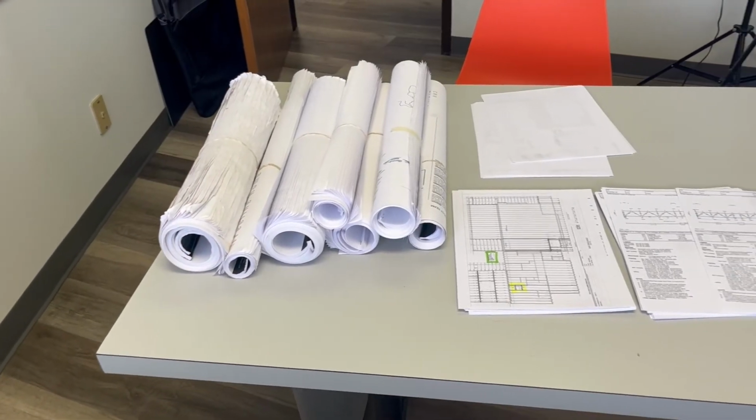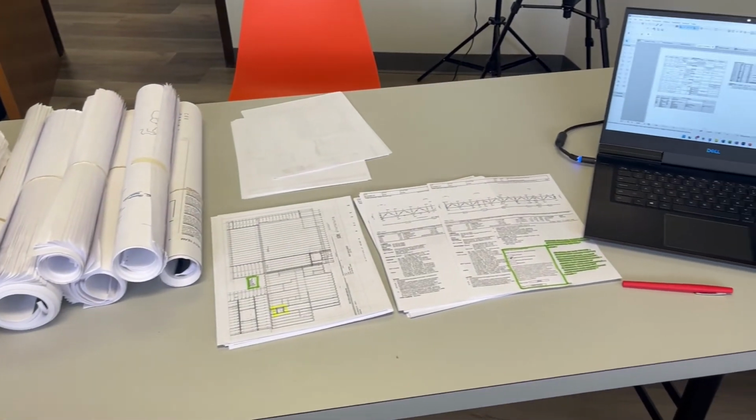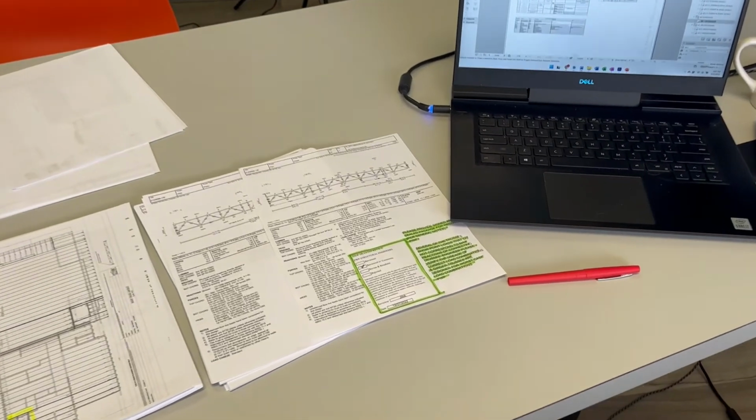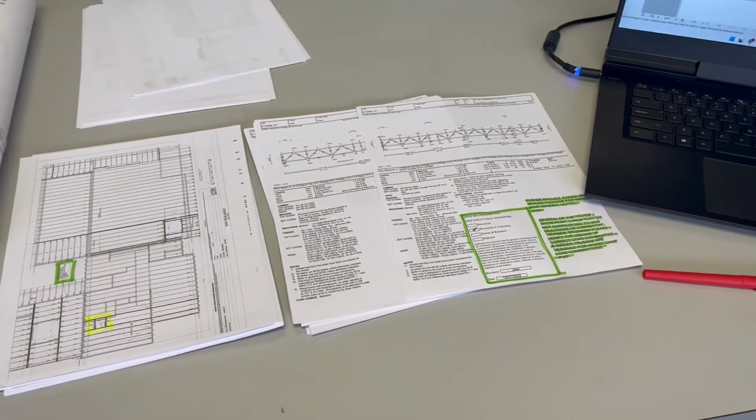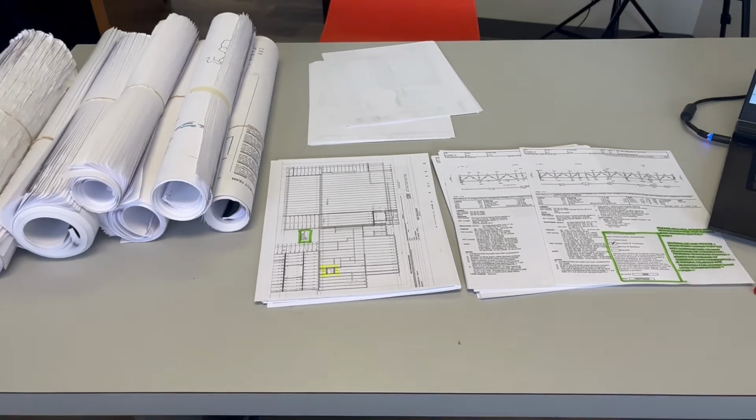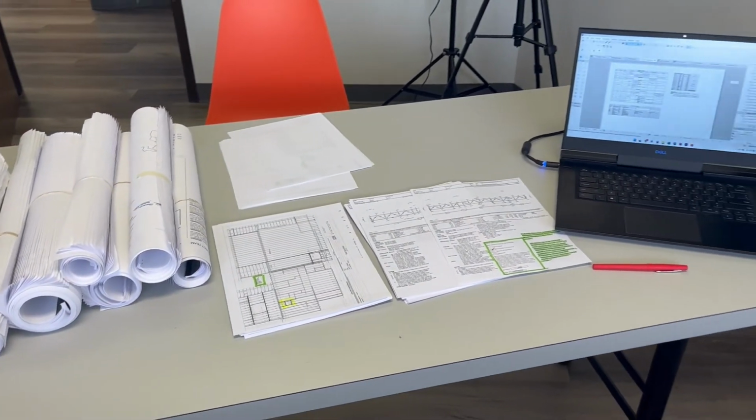Another important factor of construction administration is reviewing shop drawings. Typically, the architect will receive shop drawings from steel fabricators, truss companies, and all sorts of other folks that are actually putting together drawings for the folks inside the fabrication facility. These drawings are then compared to the construction documents produced by the architects and engineers. The point here is to make sure that the design intent is being communicated effectively into the shop drawings. This typically is an important step before they go into the manufacturing of these different products to avoid any errors on the site. So there you go, the 6 phases of design.